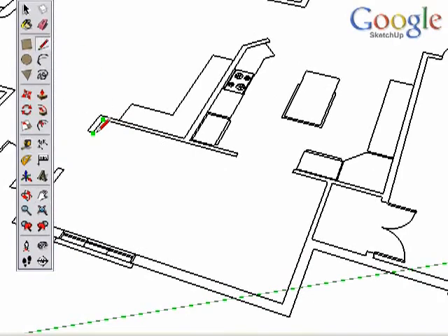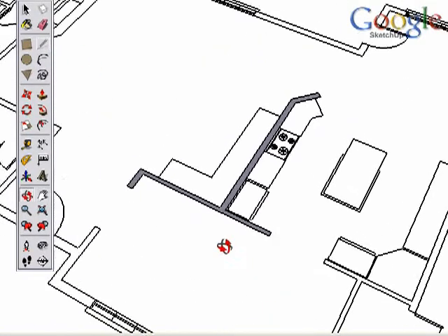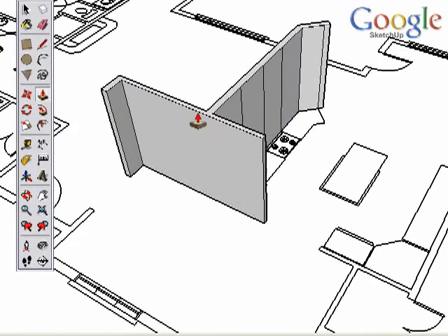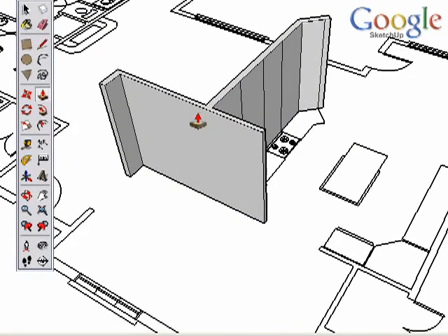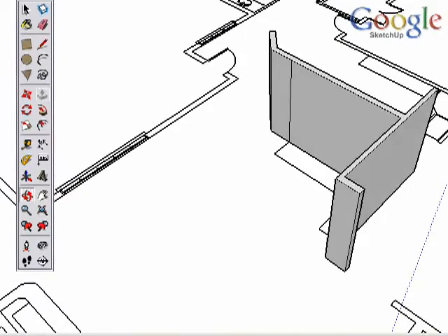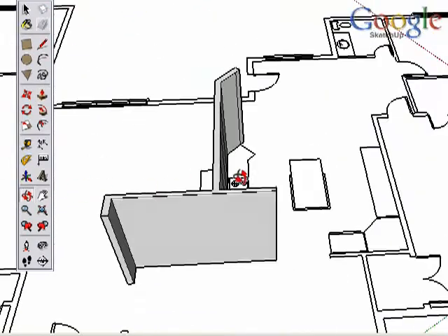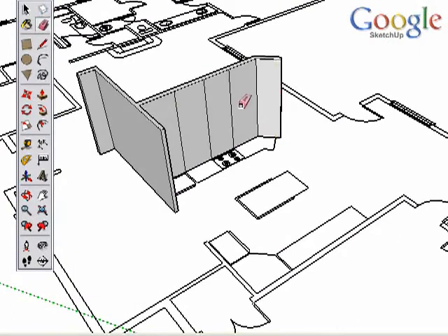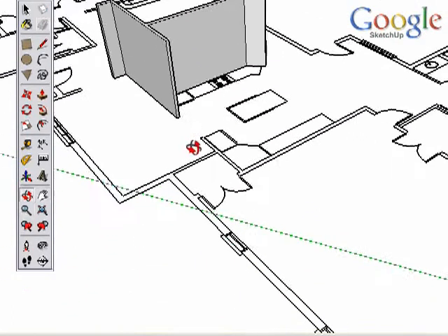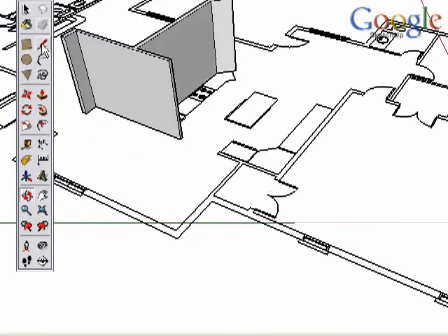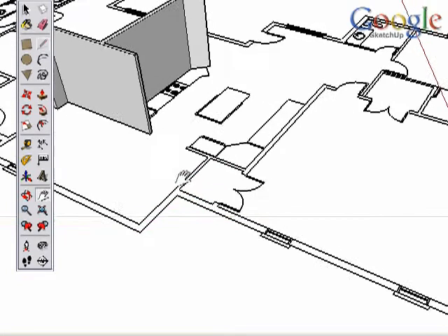Now this is a previous method for using CAD files. You trace over an edge, creating a surface, and then be able to pull that up. Now this creates some unnecessary lines that you need to clean up. Usually that's not too big a problem. The problem comes here. As you're working around your model and trying to create surfaces to pull up, sometimes it doesn't work. As we trace over these edges, nothing happens.